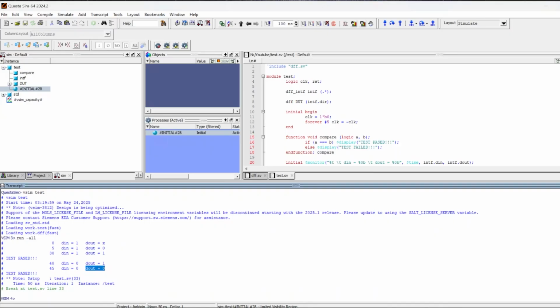But for some large designs, some projects in which you are connecting a large number of modules, let's say around 15 or 20 modules, and each of those modules has lots of signals which are not common to each other, then if you want to change a common signal that is shared amongst those modules, let's say the width or the data type, you can still parameterize it, but it is more error prone, and interface just solves that.